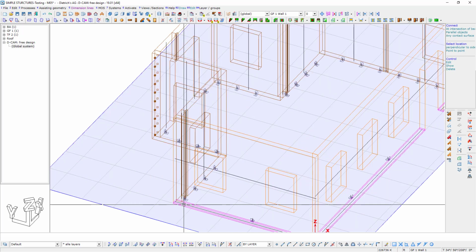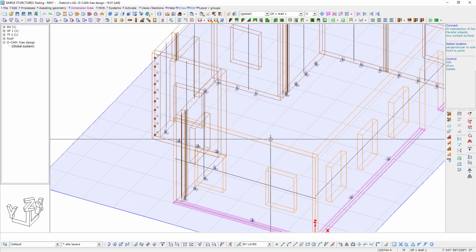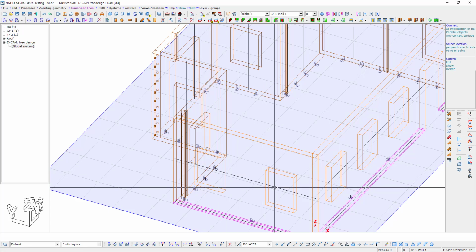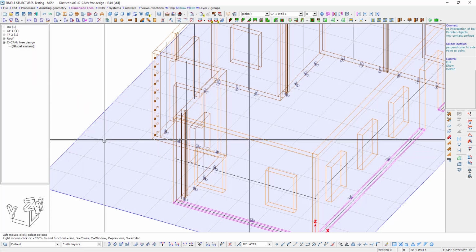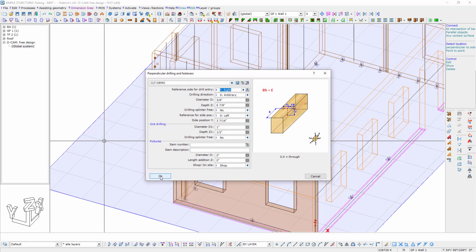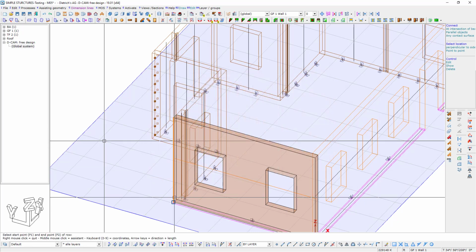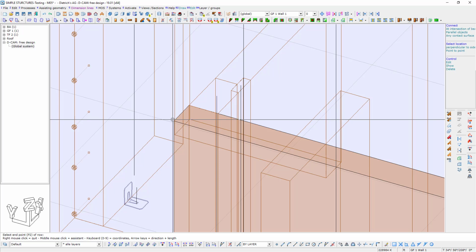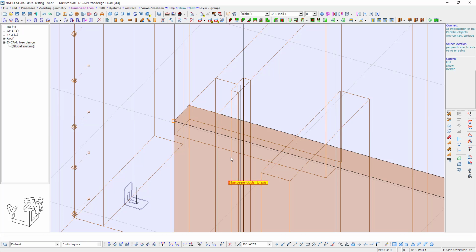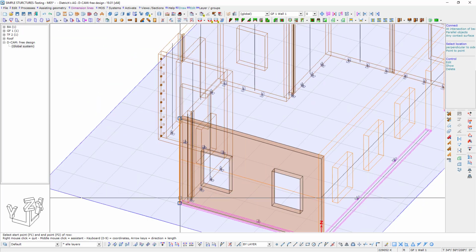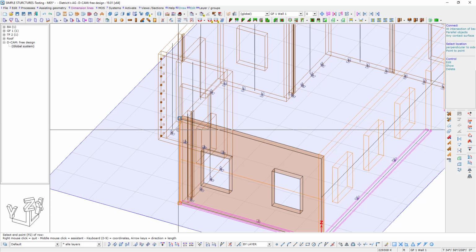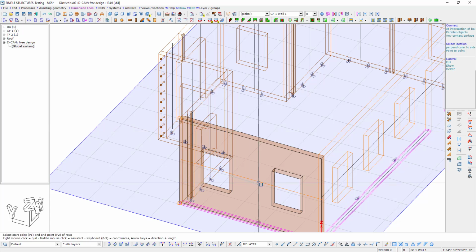And let's go now to the panel here in the front with the horizontal orientation, and we'll see how we do. So I'm going to choose again processes, drilling perpendicular to side. Select my object, select OK, same settings, local array, my origin. I'll zoom in here so I click on the correct thing, and you'll notice that, let me do that again. I'll click my origin, my end, and you see this edge perpendicular to axis.